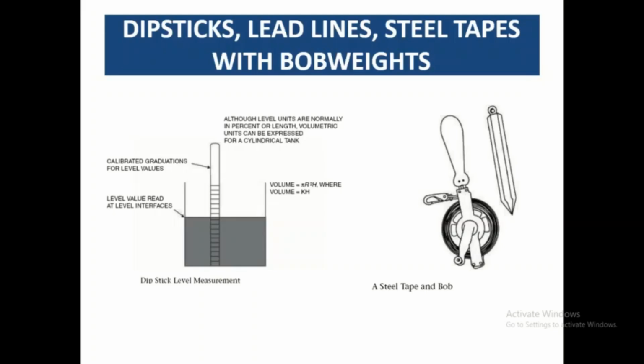On the other hand, there are methods where you insert the off-spec material with your raw material in a minimum amount, 2 to 3%, not more than that at all.